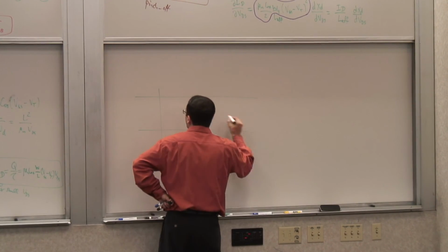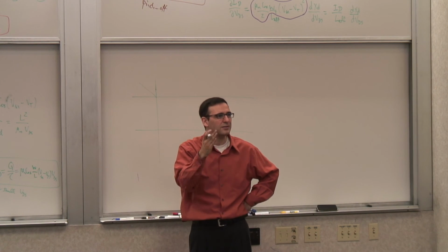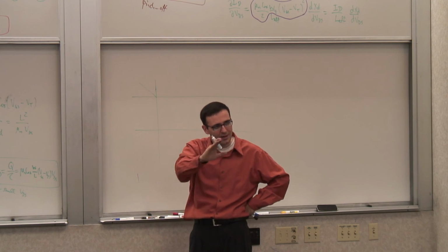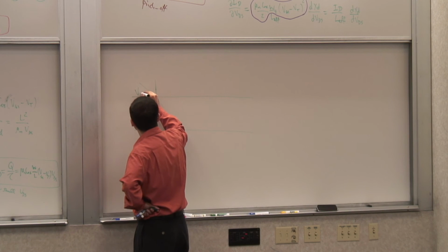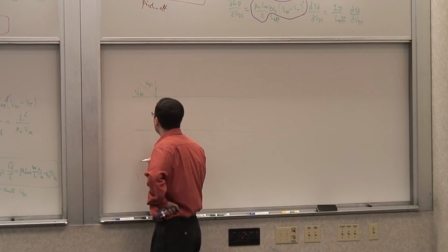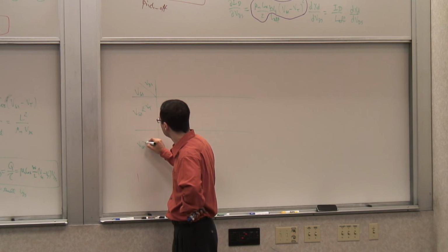So now we have two primary controls of the transistor. Well, we have really three: the VGS, the gate voltage, the drain voltage, and the bulk voltage. But let's say we don't worry about the bulk voltage for now, and worry about VGS and VDS. Now, there are two modes: VGS smaller than VT and greater than VT.